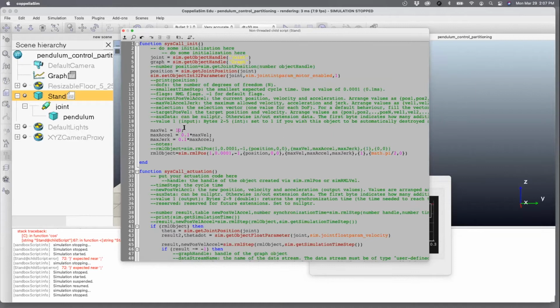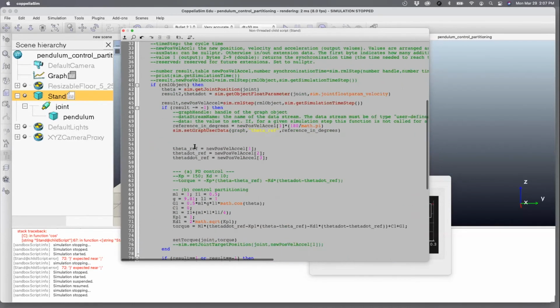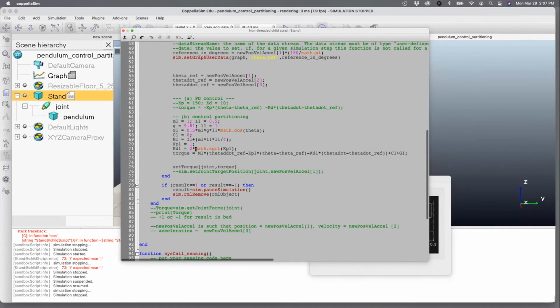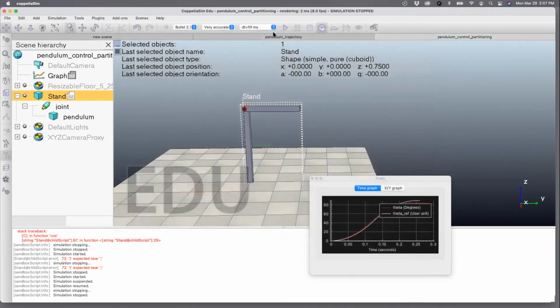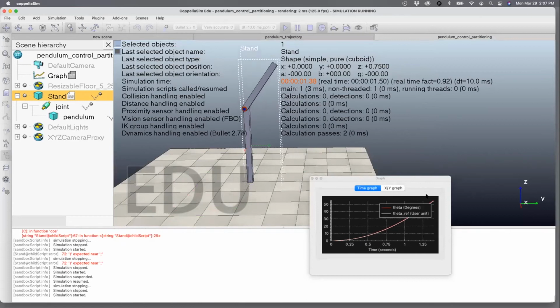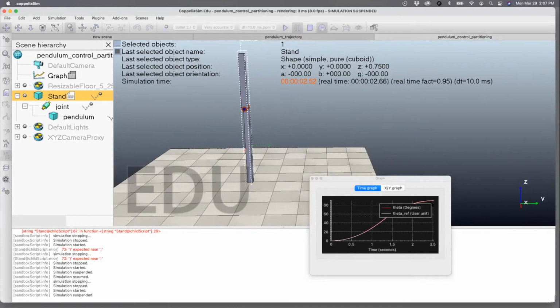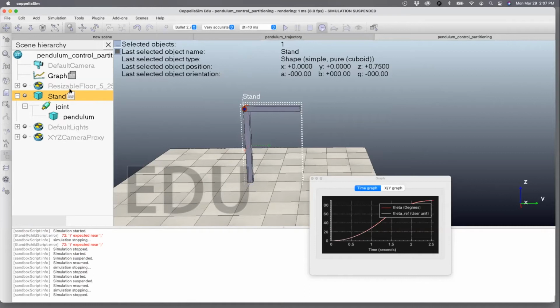I should just start slow, right? Let's make it 10. Okay, and then make this Kp as 10. Okay, let's just do 1 first. See what happens. So you can see that the tracking is phenomenally good. It's bang on with just a gain of 1.